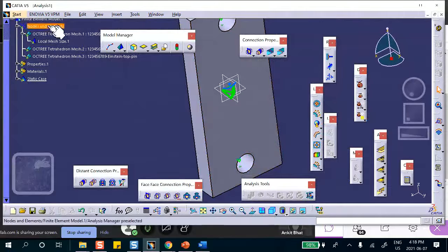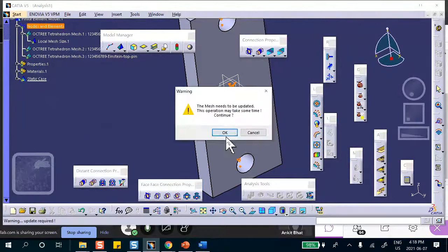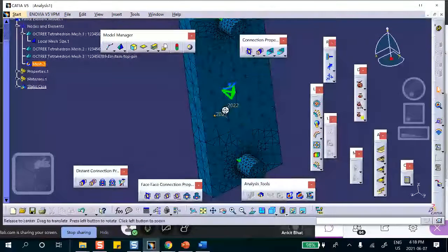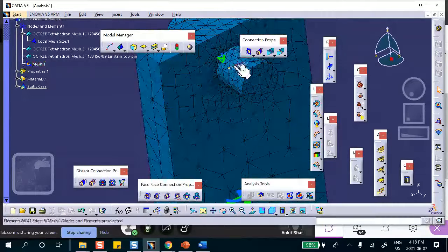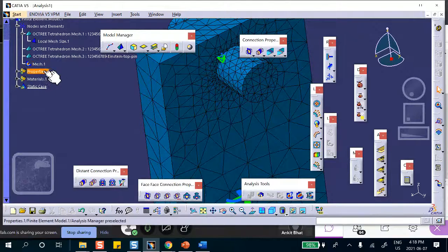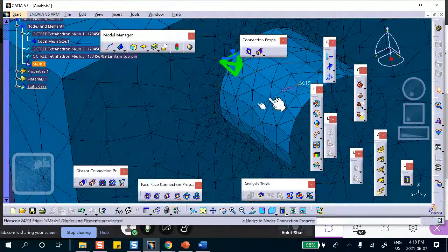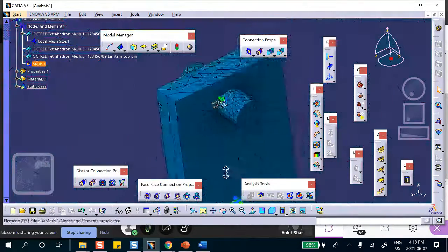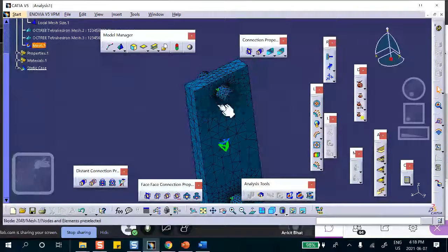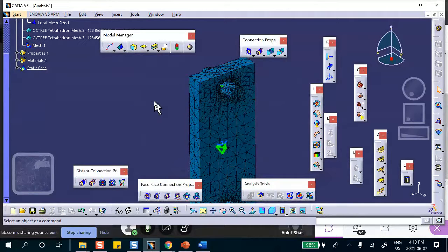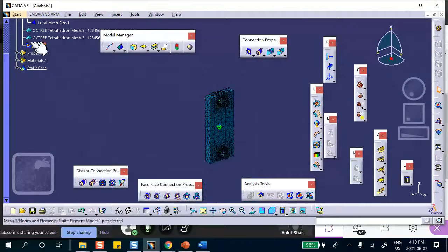Now, if you look at your mesh, right-click, mesh visualization, in the middle section, it's that big, but you get close to the ends, close to those holes. You see that? Even if I hit this, let me hide. Right there, you see this? It didn't do any refinement for the pin, but it did it around the hole, okay? I didn't want you to refine the pin, I just said one side. Basically around the hole. I said very explicitly around the hole, in the block, not the pin. All right, so this is good.